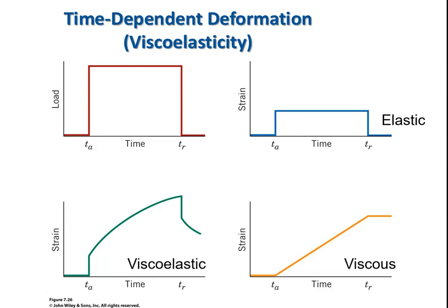Particularly, we started our lecture discussing metals specifically below 1/3 of the melt point. So if we get above 1/3 of the melting point, metals will start to display these same kind of characteristics. So it's just a difference in temperature relative to melt or glass transition for the particular material. So we will see that next time, and see you then.